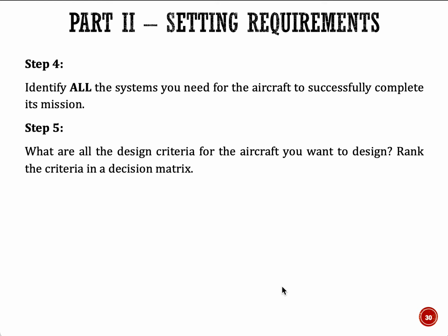If minimizing radar cross section is a priority to you, you may have to set that as a criteria, so that you can shape your airframe based on that. So there's a lot of things to think about depending on the type of aircraft you're designing, right? And that's something you will find out once you do the historical buildup.